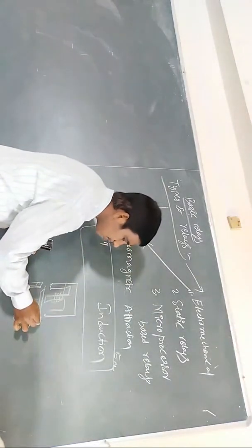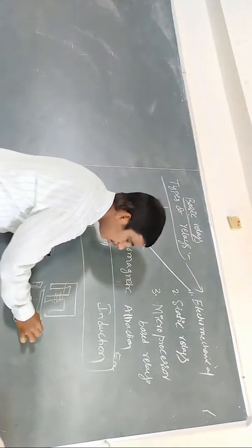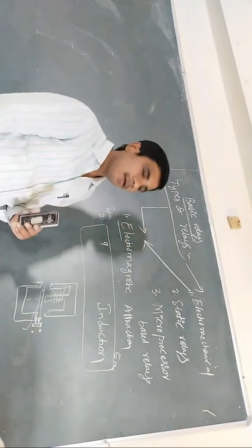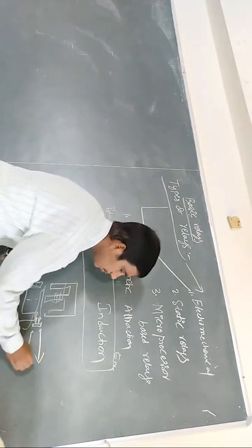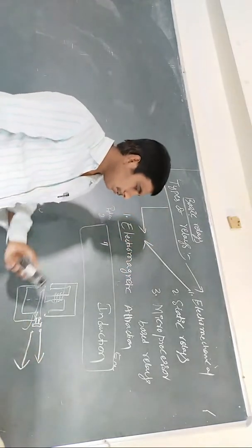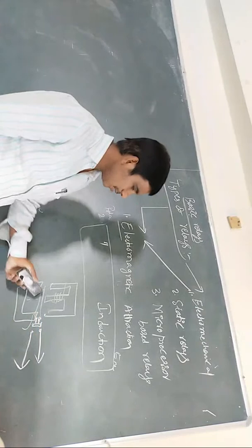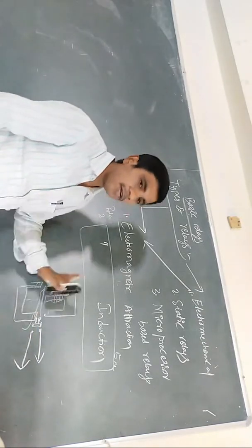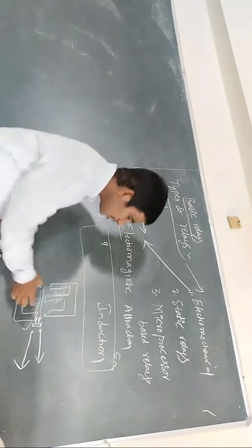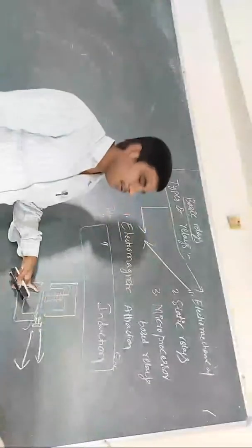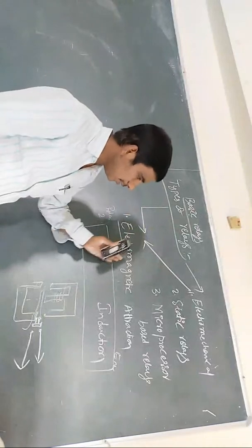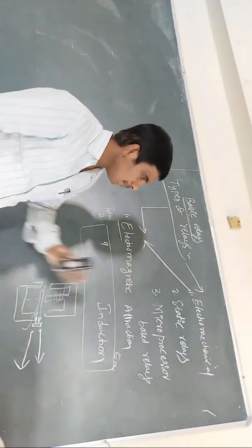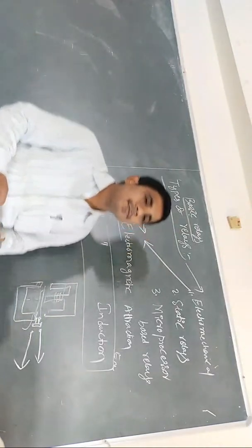For the disc we attach one NO-NC contact. These terminals are connected to the circuit breaker. This is the induction principle. The disc continuously rotates. Whenever a fault occurs, the disc tries to rotate. Under normal conditions, the disc will be in an inoperative condition. That is the induction type relay. One by one we will discuss in the next class.